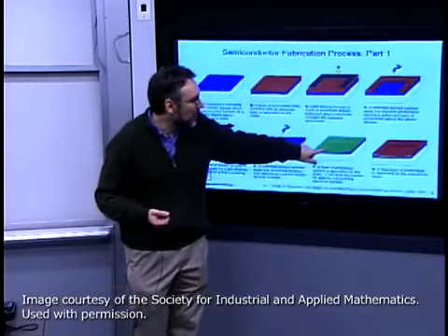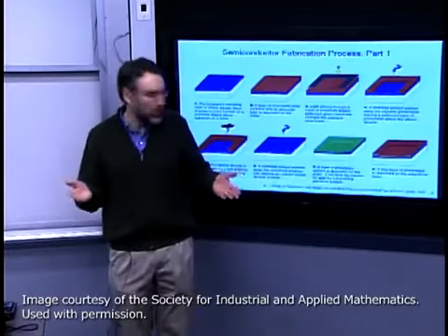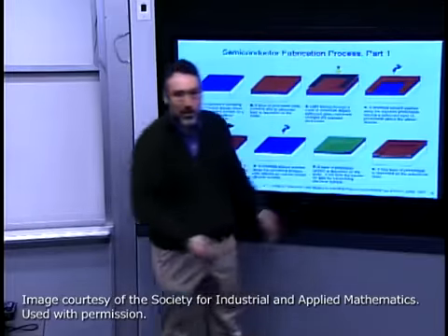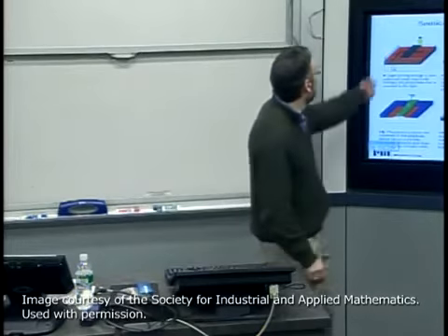So we've deposited that. Recall, what geometry do we want? We want this thin gate electrode, so we're going to do a photolithographic step again to do that. Deposit photoresist, expose, in this case, here again, another positive photoresist case.